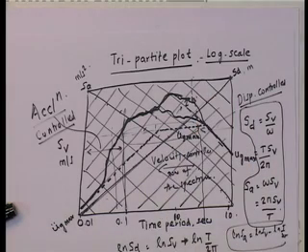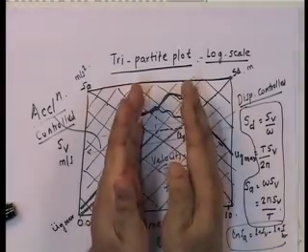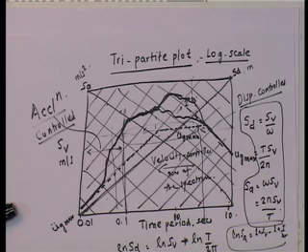In this zone, the peak ground displacement is what is going to determine the peak response of the structure. And in this region, it is really energy controlled. Okay. So, therefore, short period structures are acceleration controlled. In other words, they are force driven, inertial force driven.